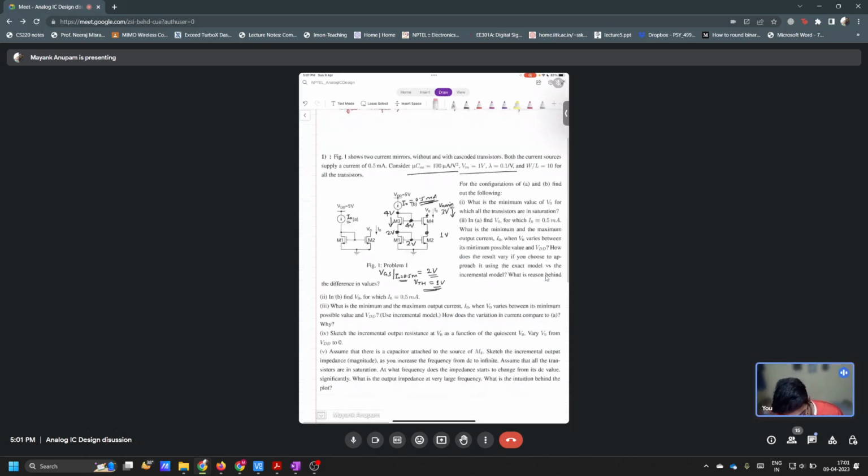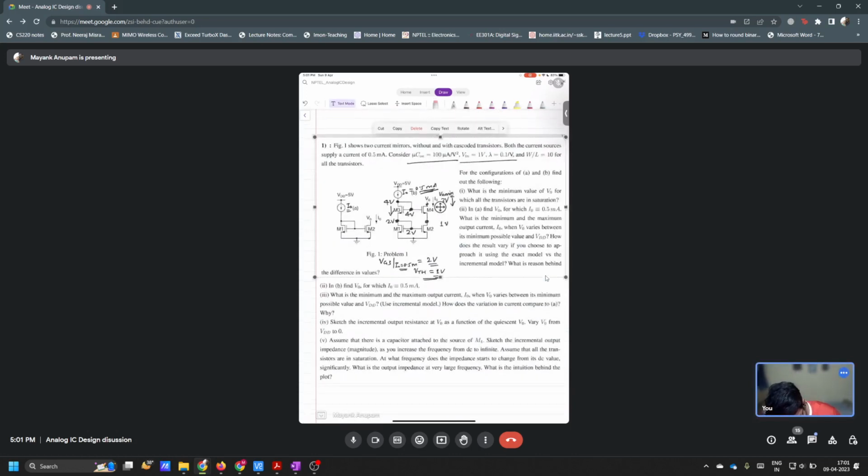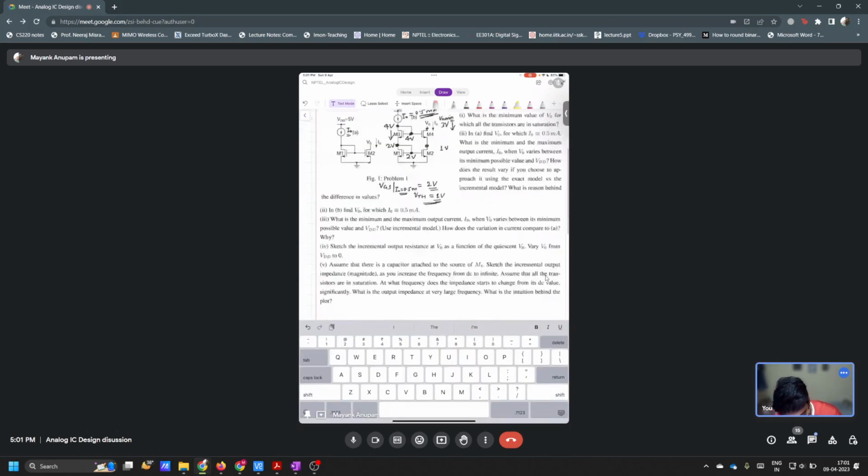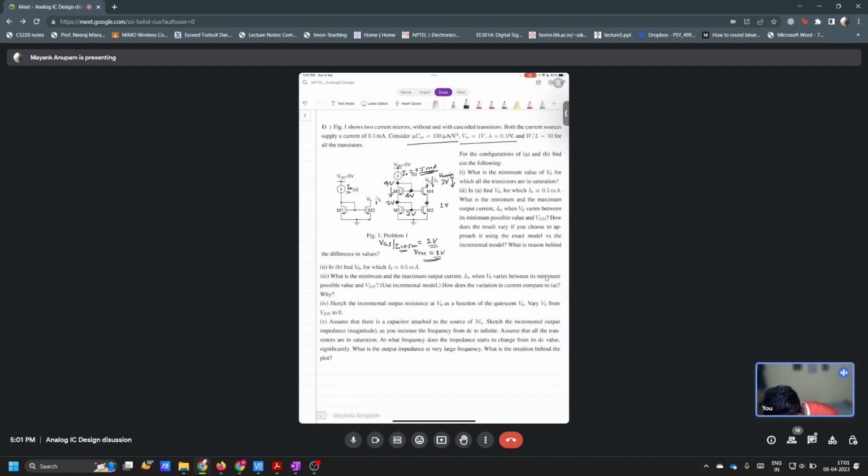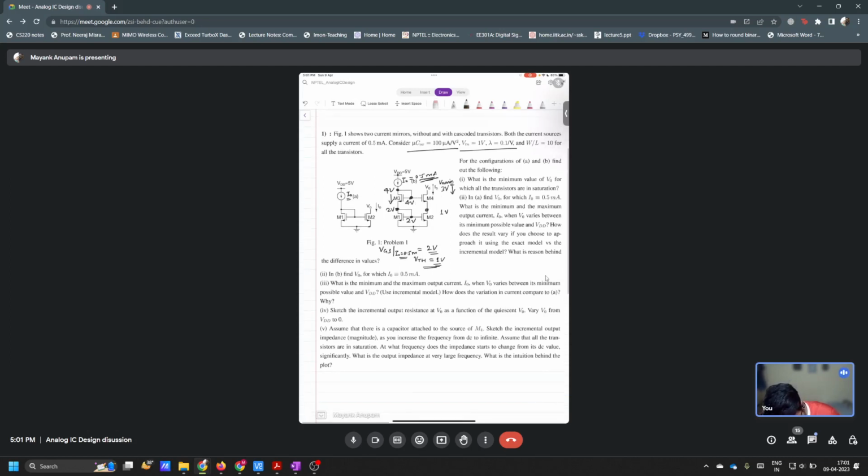Yes, clear. Fine. So I was saying that always remember that in a cascode connection, this is a cascode connection here, output. If the output of this cascode starts to go down, then what will happen? The first transistor that will go out of saturation, the one most susceptible, will be M4. Always remember that. I mean, for properly biased cascodes, that is the general thing. This cascode transistor will be the first one to go out of saturation. Only after that M2 goes out of saturation. That is in general how it is biased also.